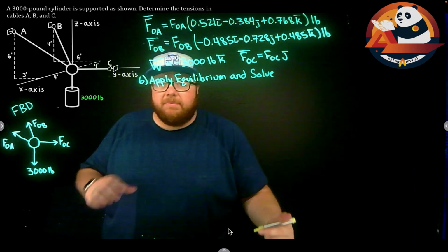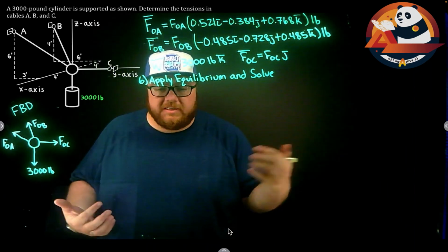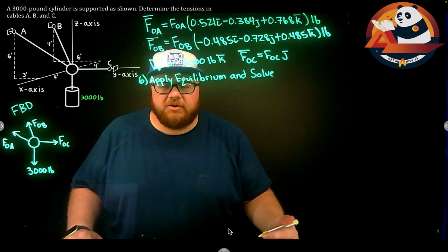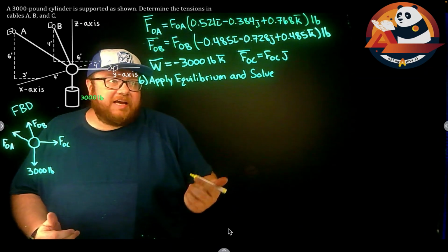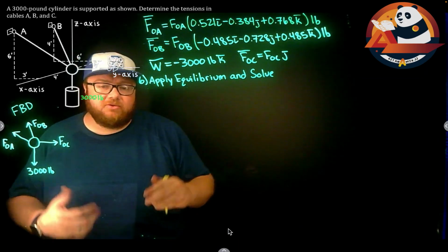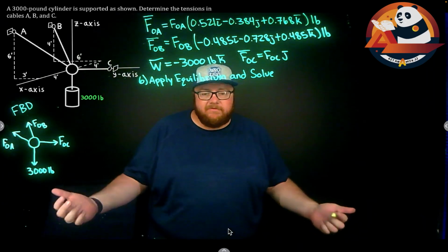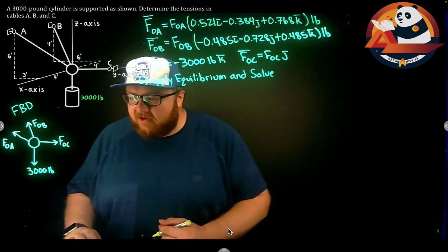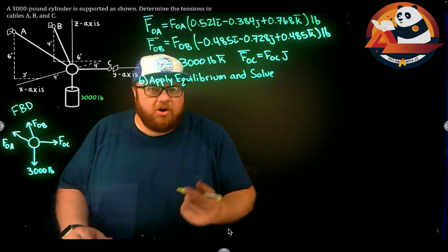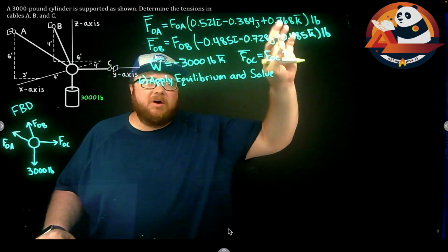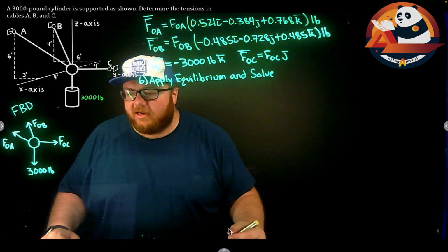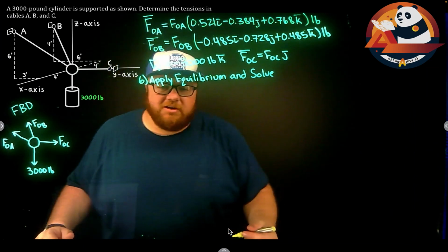So in 2D, when we applied equilibrium, we just summed forces in the x and the y, set our equations equal to 0, and found our unknowns. Really, we're just adding in. We also have k terms, or z directions now. I can add that in, still set it all equal to 0, find my unknowns. So if I'm doing this, I would start out and just go for it. Sometimes we can do one equation, find one unknown immediately. When in doubt, just start making equations though.